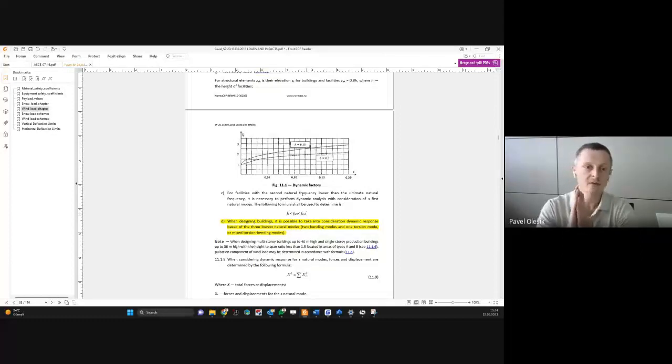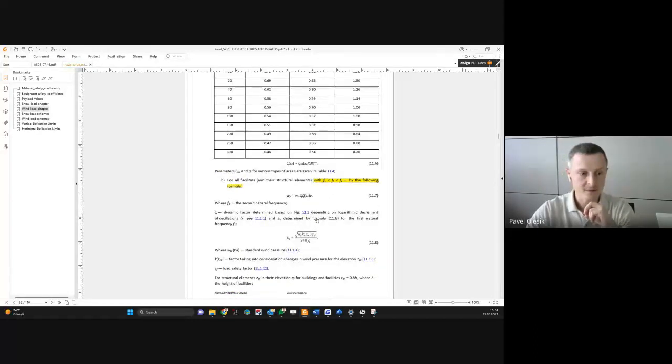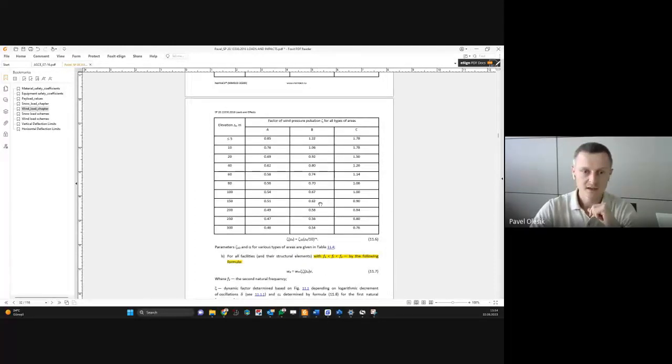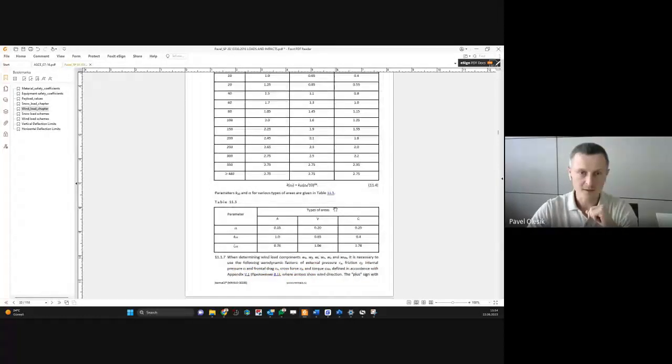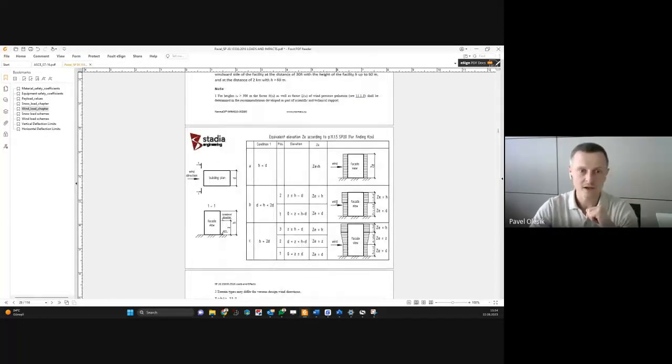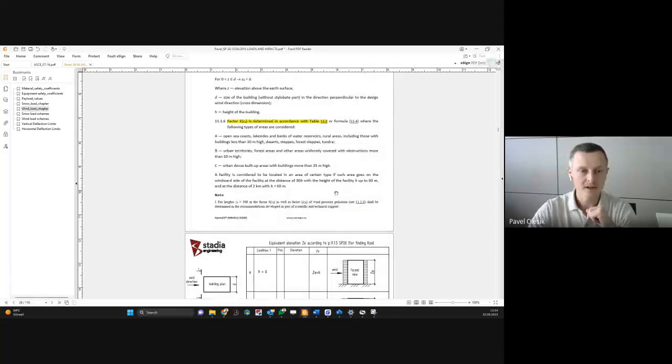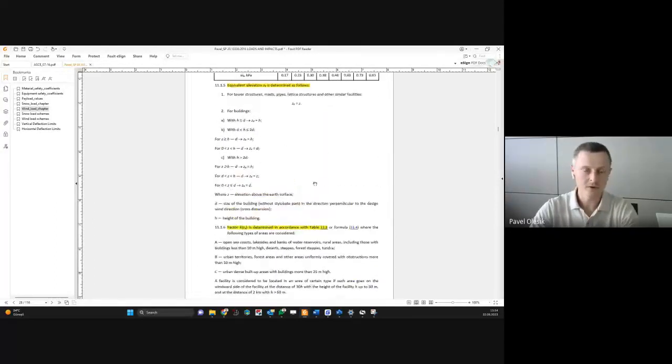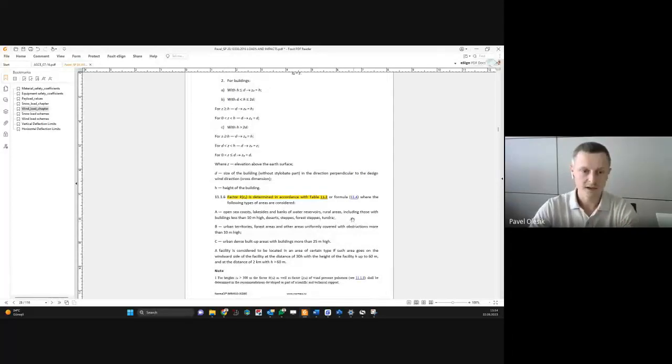But in different Russian programs, finite element software, we have automatic calculation of this wind load. For example, Lira support can do this. Some utilities for ETABS can do this. You should check this load anyway. But instead of you, the calculation program will do it, and you should check just that this is taken into account by the program.